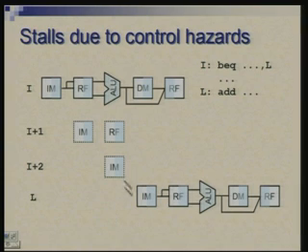Okay. So just to revise, one was to not do anything, wait till the decision is done, and then start the right instruction. So the choice is between actually I plus 1 and L. So even if it is I plus 1 to be done, you start it here. The other approach says that okay, start something in anticipation. If it is I plus 1, you have gained something. If it is L, you have not lost anything. All right, you lost something which was to be lost in any case.